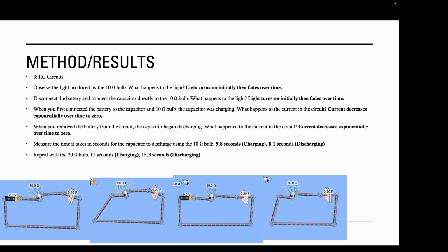And measure the time it takes in seconds for the capacitor to charge and discharge using the 10 ohm bulb. So when charging, it took 5.8 seconds, and when discharging, it took 8.1 seconds. When charging with the 20 ohm bulb, I timed it. It took 11 seconds, and for discharging, it took 15.3 seconds.